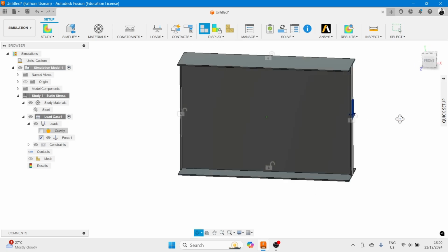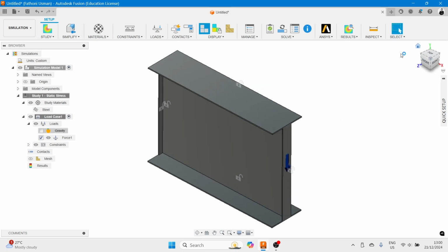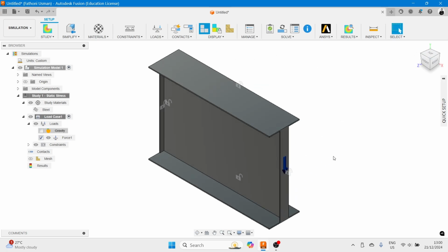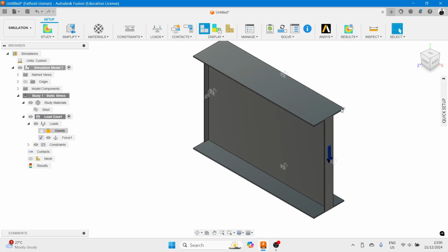So based on our calculation in this design example, the buckling strength, the buckling capacity, buckling design resistance of the girder at about this size is about 2300 something, or 2700 something, I forgot. You can check in the design example that I sent to you.